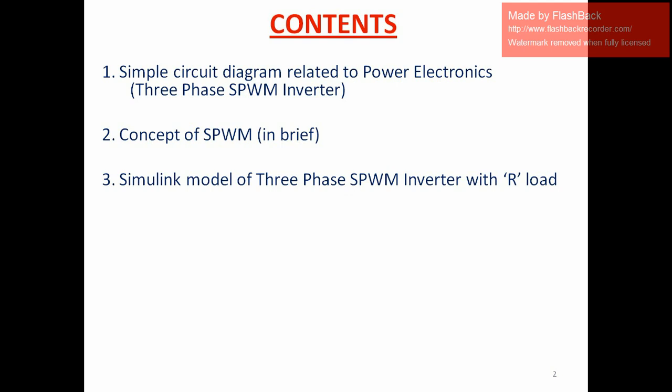Third point of the content is the Simulink model of a three-phase SPWM inverter with R load. So we have selected R load and a three-phase SPWM inverter with R load, and we'll be preparing a Simulink model for the same, and we'll be discussing a few outputs. We will be studying a few outputs with the resistive load.